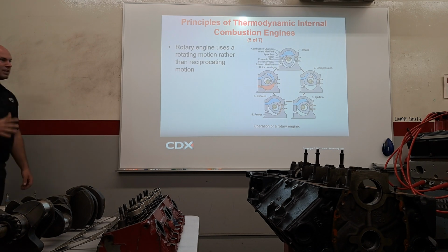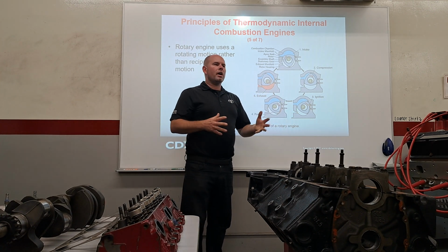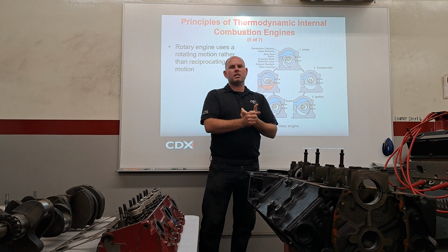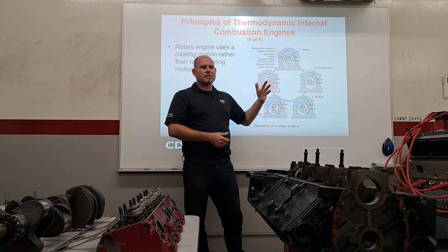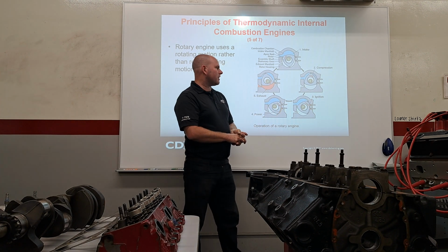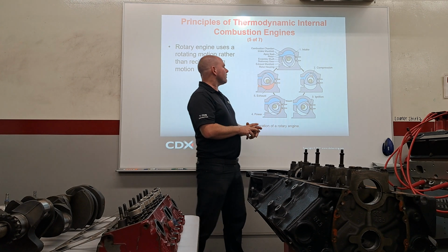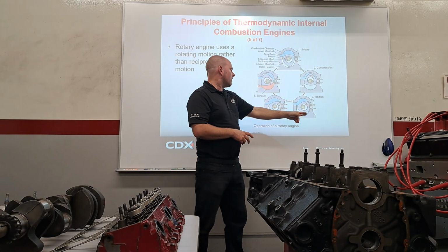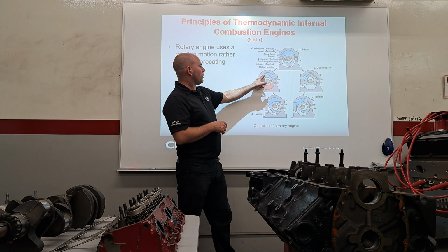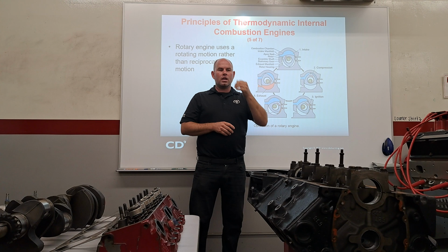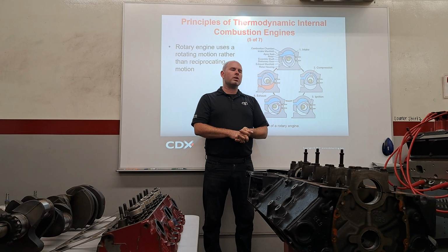Now, here's kind of what we were saying. These are all engines. So a 2-stroke air-cooled engine, very basic. You could get a little more complex and go to a rotary. A rotary is kind of weird. There's no valves, there's no cam. They're small and compact. If you look, we have an intake, a compression, where the ignition occurs, which is not a stroke, the actual power stroke, and the exhaust stroke, but we have it happening in multiple chambers. So to say an internal combustion engine definitely has pistons is not real accurate. It could actually be this rotary right here.